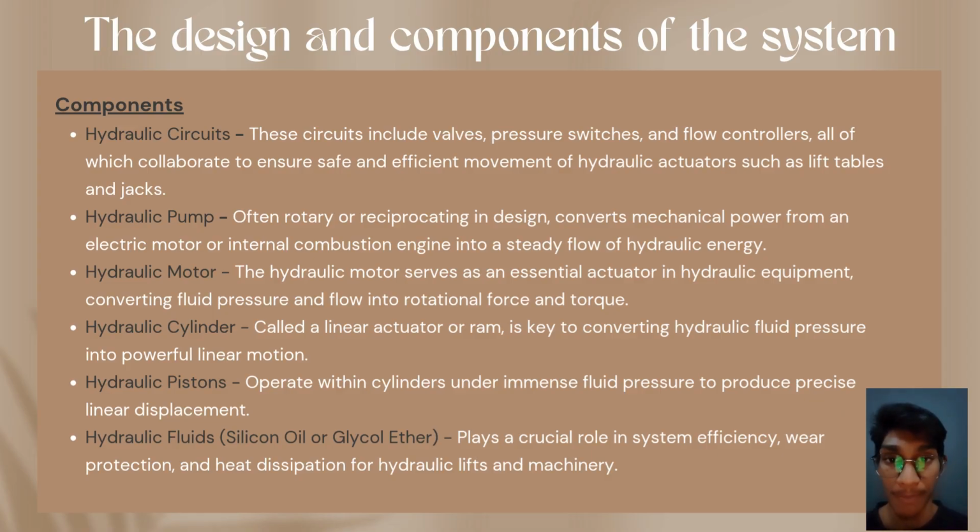Next is the hydraulic pump, which is often rotary or reciprocating in design, and converts mechanical power from an electrical motor or internal combustion engine into a steady flow of hydraulic energy. Third is the hydraulic motor. The hydraulic motor serves as an essential actuator in hydraulic equipment, converting fluid pressure and flow into rotational force and torque.